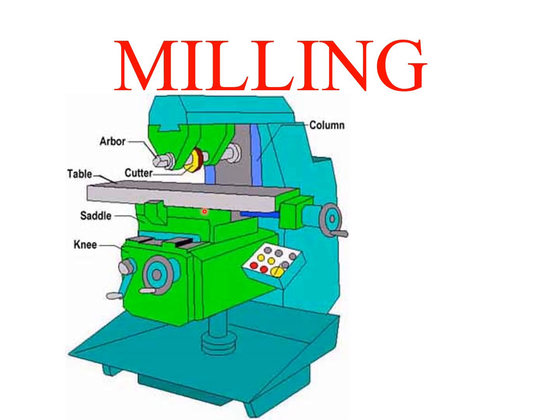And some cutting parameters used in milling. Spindle speed of revolution determines the velocity of the cutting edge relative to the workpiece, namely cutting speed. Since the cutting speed has a great effect on tool life, the selection of cutting speed relates closely to the durability of the tool.